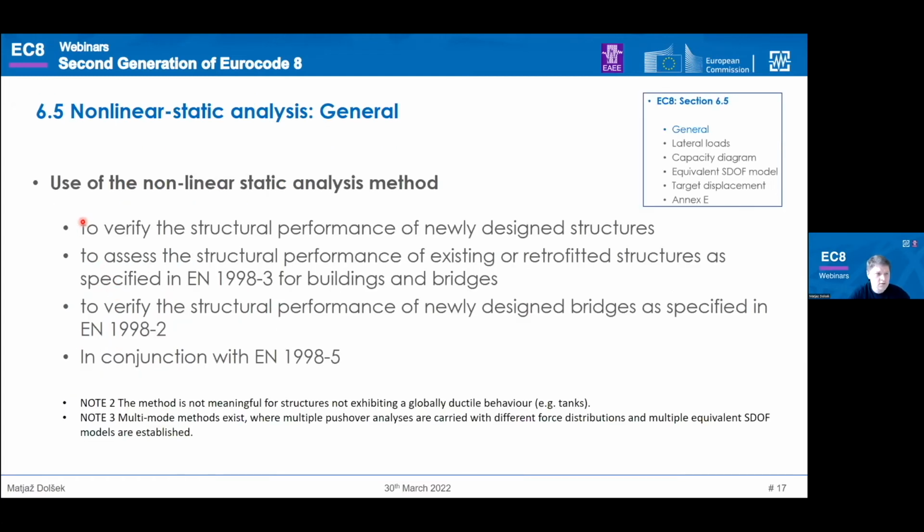If you go to the general part, the code says where, when, and for what purpose we can use the nonlinear static analysis. First, to verify the structural performance of newly designed structures. This is new in comparison to the current version. Second, to assess the structural performance of existing or retrofitted structures as specified in Eurocode 8.3 for buildings, which is now also new for bridges.